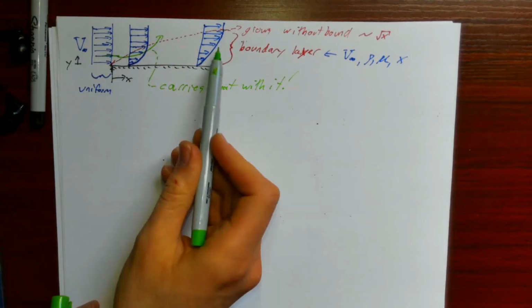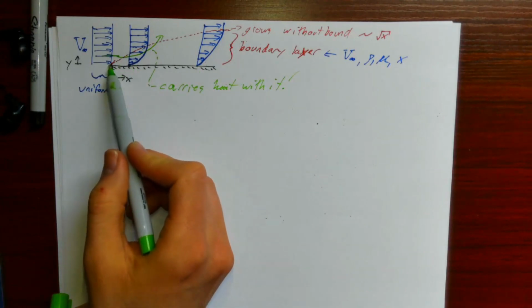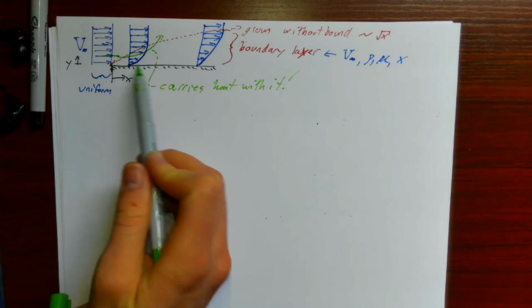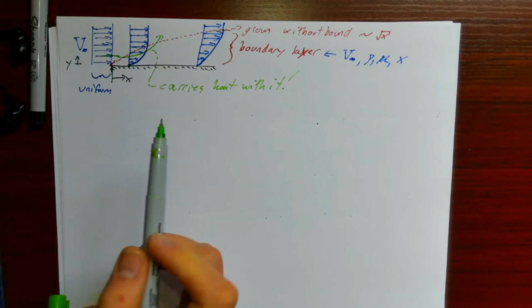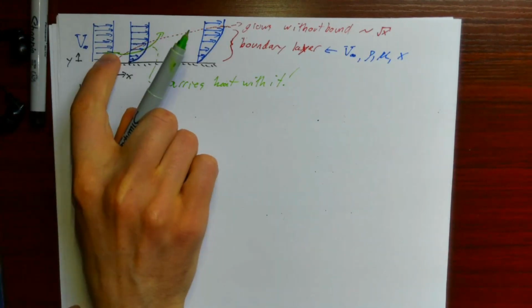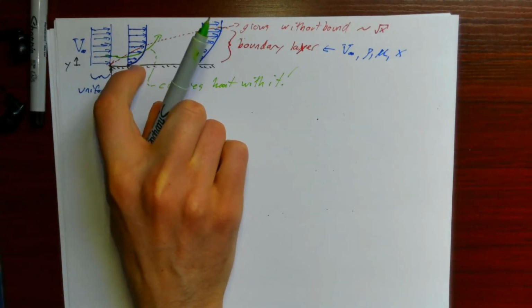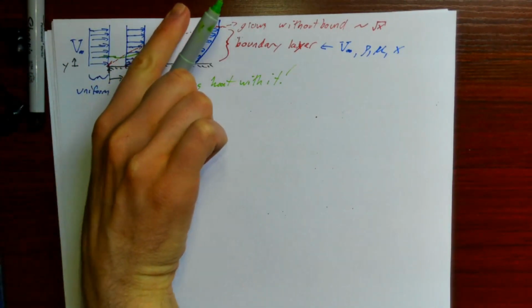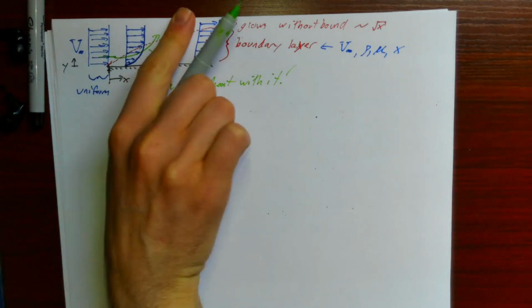I mean, we do care about it from a hydrodynamics perspective, right? This boundary layer affects things like shear stress. If we were designing airplane wings, we would care a lot about this boundary layer, but we might care about it a lot from a heat transfer perspective too. Because if I have fluid coming in and the fluid slows down as it encounters the plate, then due to conservation of mass, some of that fluid has to get pushed out of the top of the boundary layer.